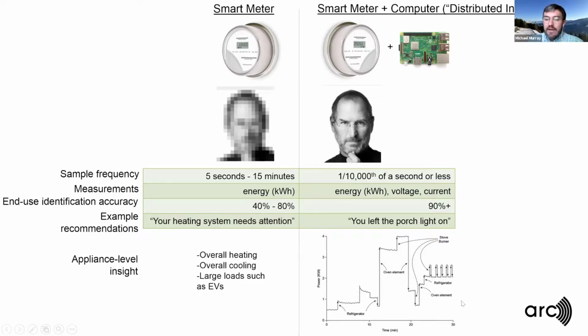So for example, on the right, you can see this is a commonly used graph in research on disaggregation in the residential sector. You can look at things like, when equipment turns on and it looks like it has a compressor cycle and it has a certain cycling and duration, well, that looks like a refrigerator. This big one that jumps on but only runs for 20, 30 minutes, that's probably your oven. And so imagine being able to have this fine level of detail in a home or a building. So you could detect things like, I have both a heating element and my compressor for my refrigeration running at the same time. Let me send a text alert to the facility manager to take a look at that.